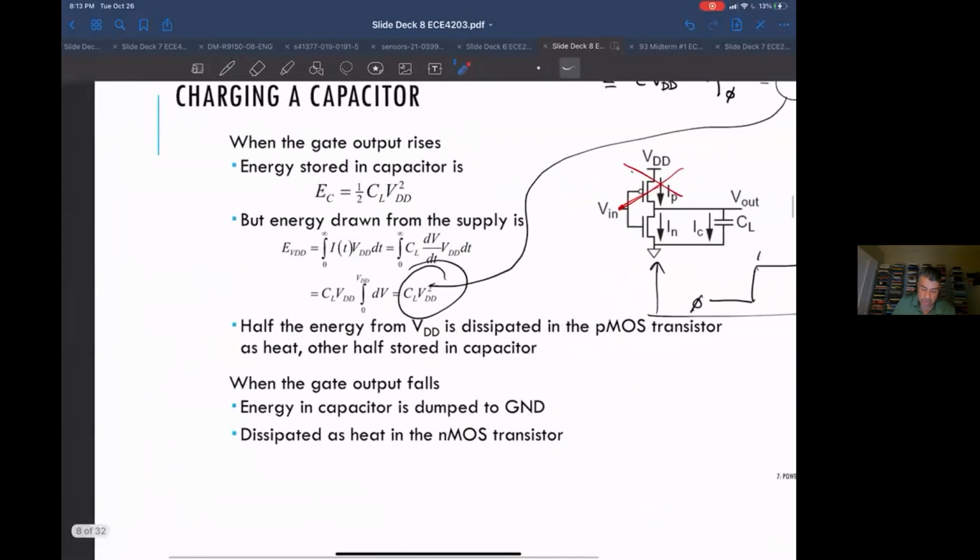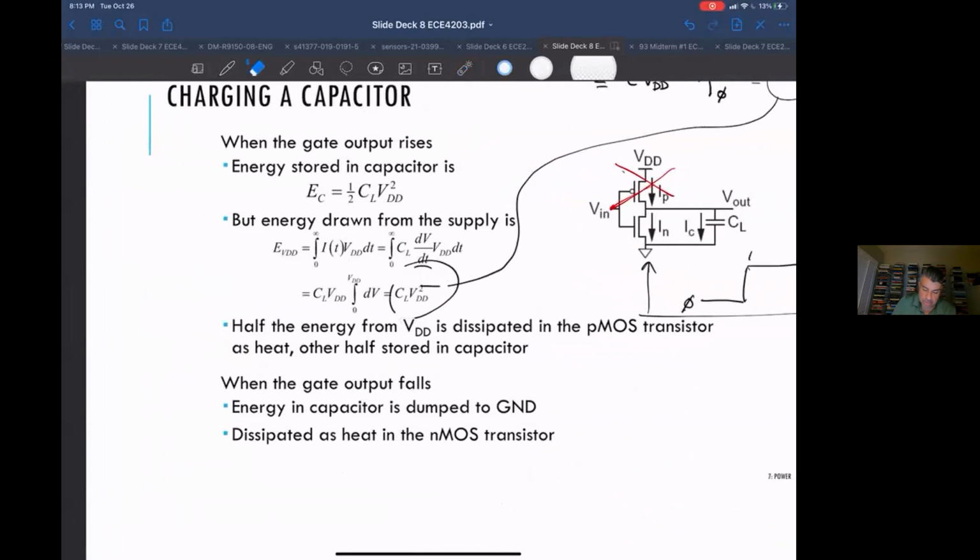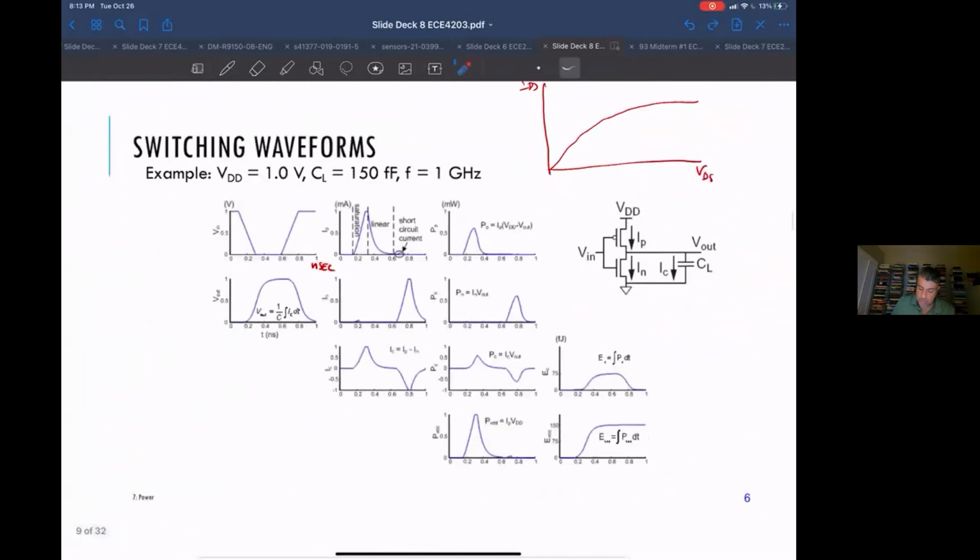Okay, again, I'll refer you guys to this equation. And we basically have a unit of power consumption every cycle where we see an output rising transition. So this frequency is important because, since this is a gigahertz, let's say this is a clock, right? A gigahertz means I get one rising transition every nanosecond. If this was a megahertz, I would get a rising transition every microsecond. So it'd be much fewer rising transitions, much less frequent.